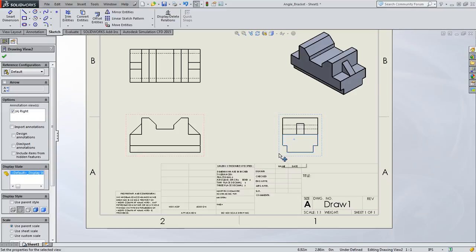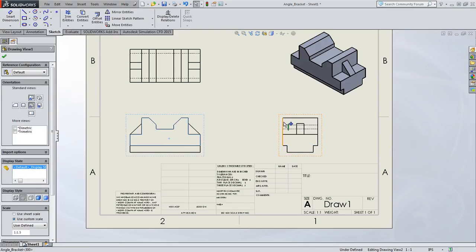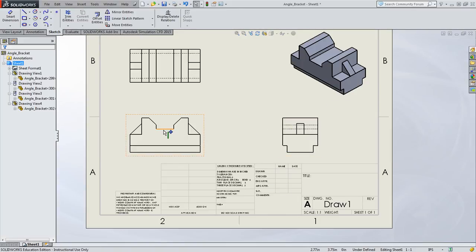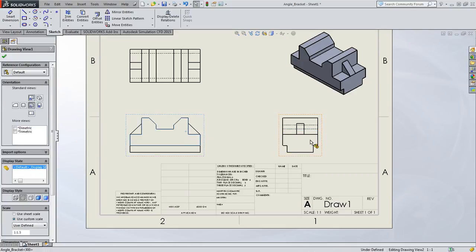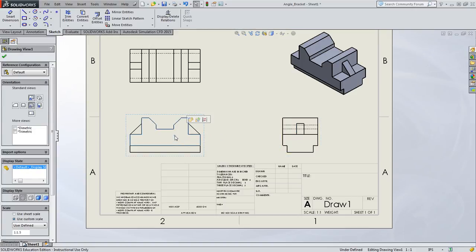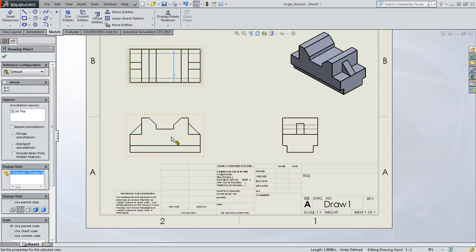In this view, I can tell someone how tall the part is, just like the front view, but also how thick or deep the part goes from the front edge to the back edge of the part. So height is shared between views, but depth is this, which is the same as this. So I can do width and depth, height and depth, height and width. Every single view can show two of three dimensions.